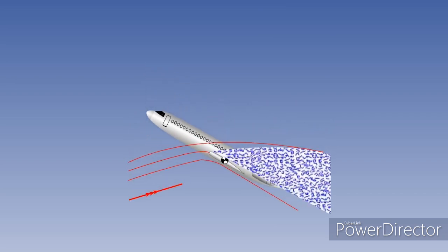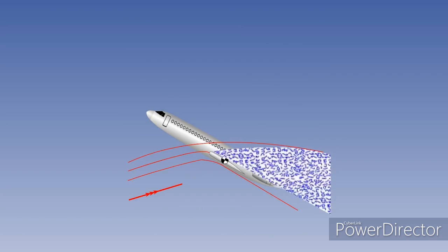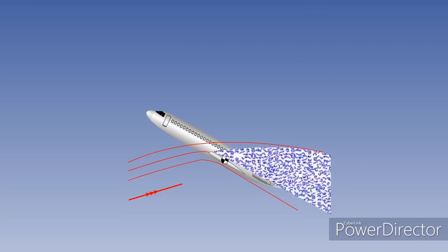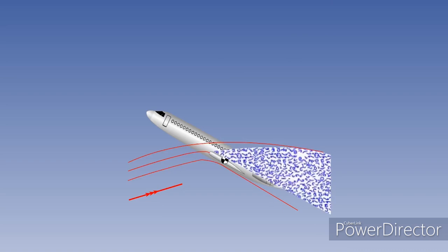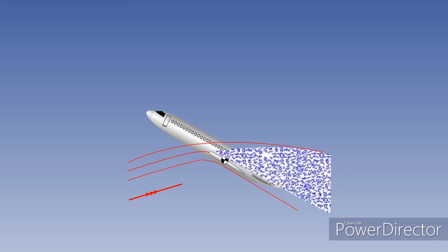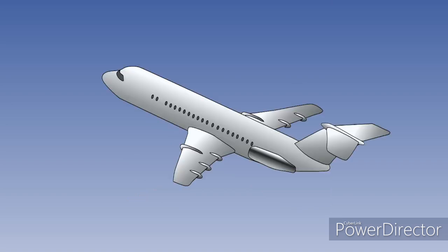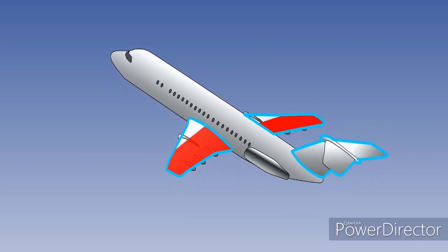Separated airflow from the stalled wing will immerse a high-set tailplane, or T-tail, in low-energy turbulent air, and elevator authority is greatly reduced, making it impossible for the pilot to reduce the angle of attack. The aircraft will become stabilized in what is known as the superstall, or deep stall. The two principal factors involved in the superstall are a swept-back wing and a high-mounted tailplane. But of the two, by far the more significant is the swept wing, with its tendency to stall at the tips, causing the pitch-up phenomenon.